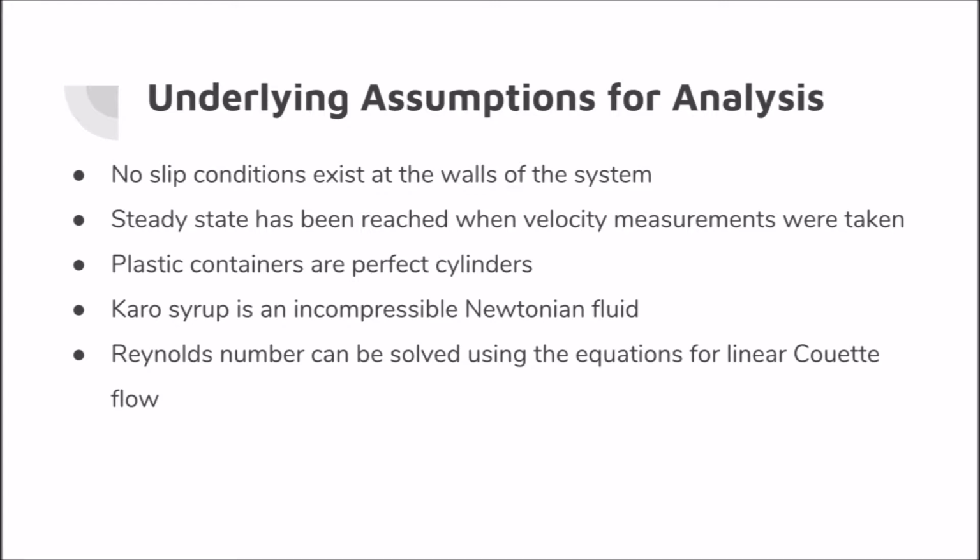Various assumptions were made to simplify the calculations. We assumed that the principle of no slip holds at vessel walls, implying that the velocity of syrup at the inner cylinder matched the velocity of the inner cylinder. We also assumed that the syrup is an incompressible Newtonian fluid for constant density and viscosity. Lastly, we assumed that the calculations for Reynolds number are analogous between standard and Taylor Couette flows.